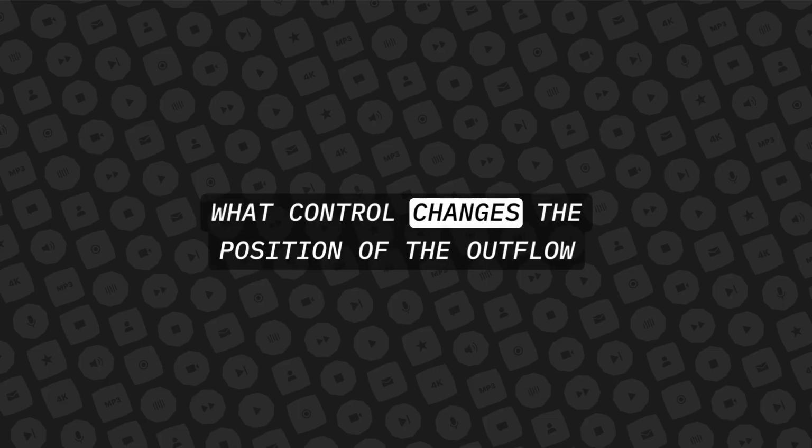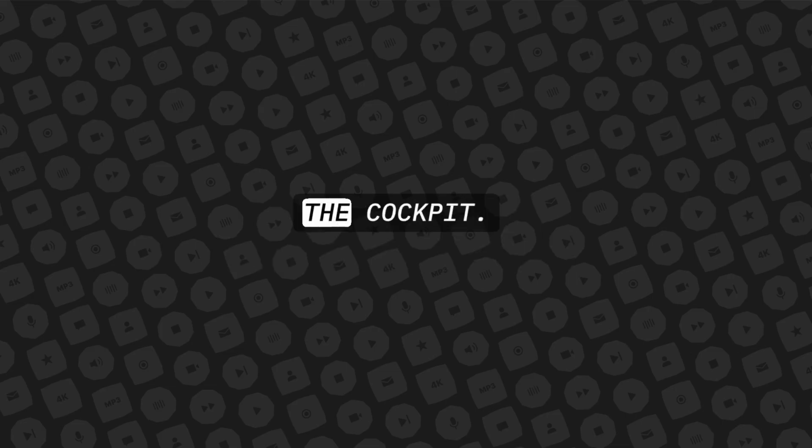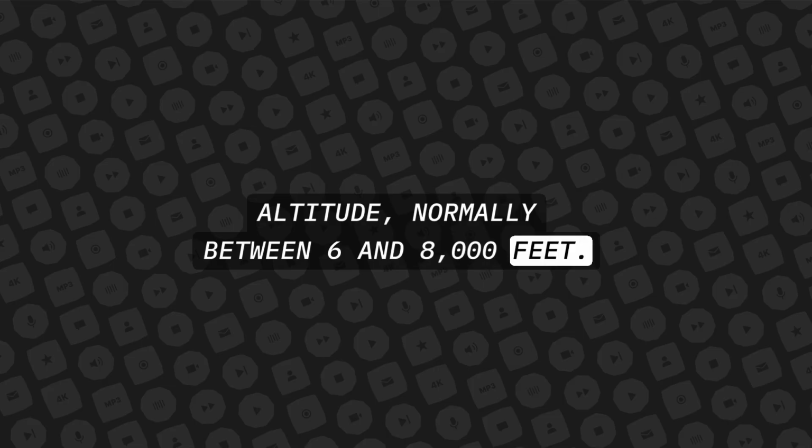What control changes the position of the outflow valve? The pressurization controller, located in the cockpit. It is used to set the cabin air pressure to a desired altitude, normally between 6 and 8,000 feet.